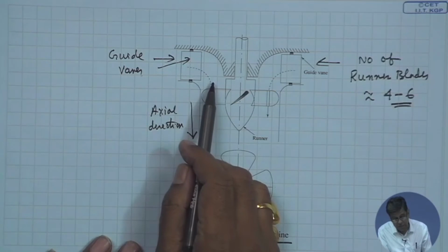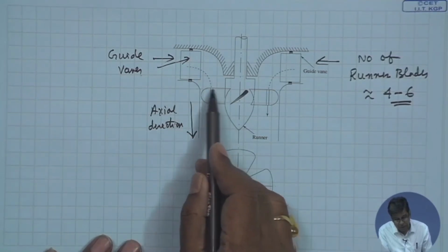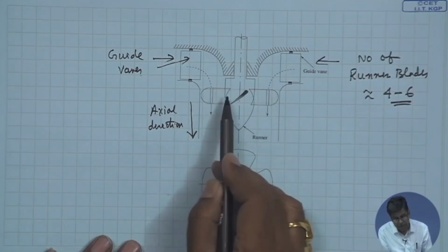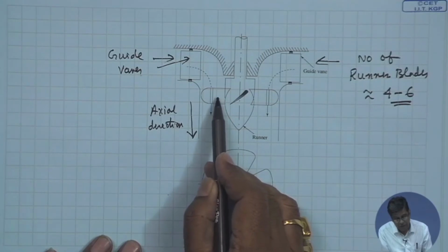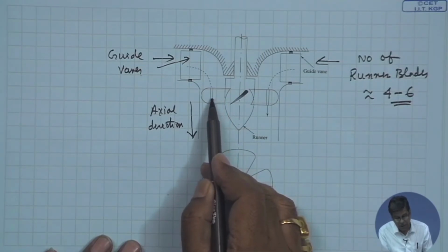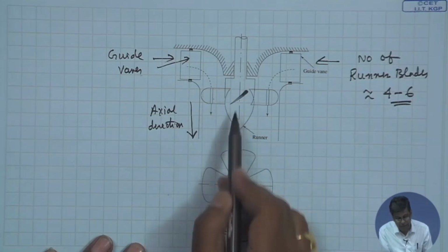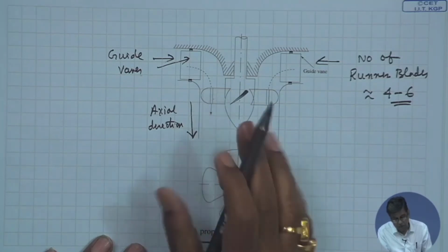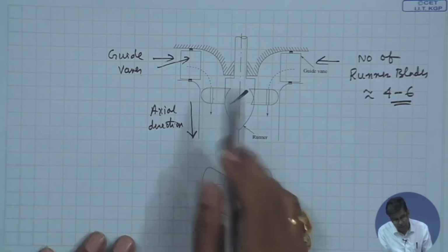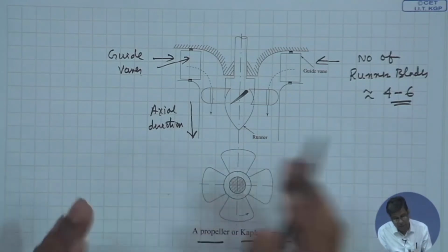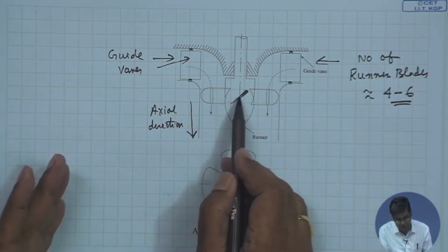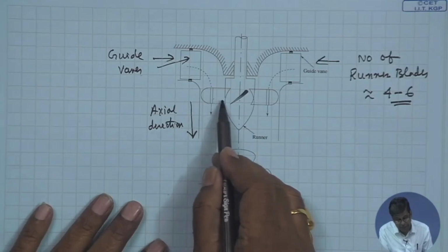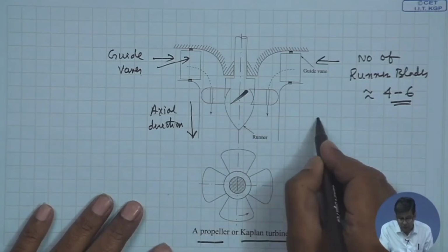It can be approximated more closely with a free vortex rotation, but the rotational motion of the blade is solid body rotation, which is a forced vortex type. That means solid body rotation, where the linear velocity is proportional to the radius of rotation, that means the radial location from the axis of rotation. A combination of these makes a complex flow of a typical Rankine vortex type, which is a mix of solid body rotation and free vortex flow. So, away from the center there will be free vortex flow, close to the center of rotation is the forced vortex flow, and to take care of that, these blades are made twisted.